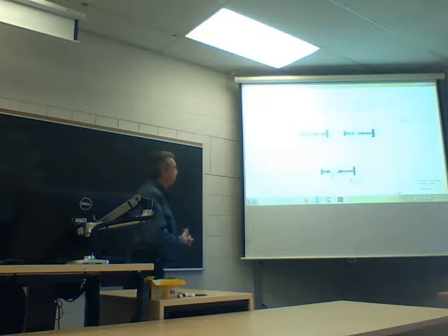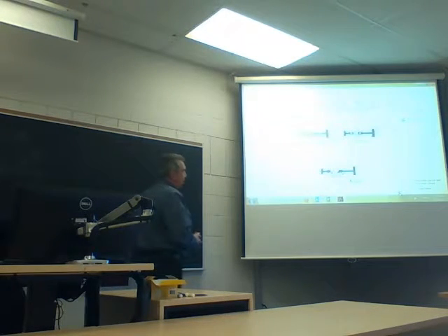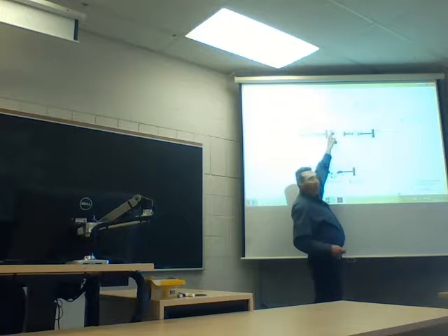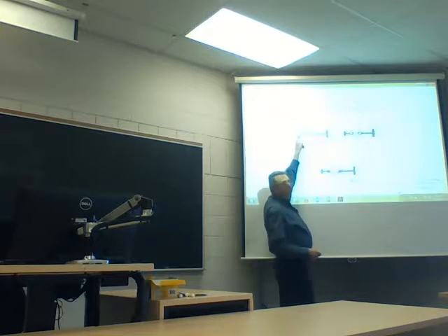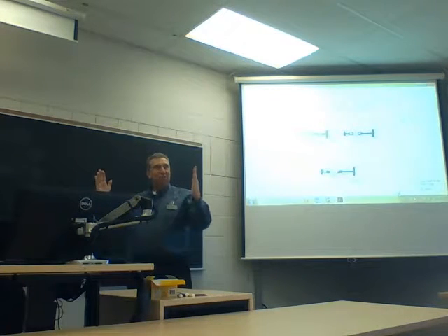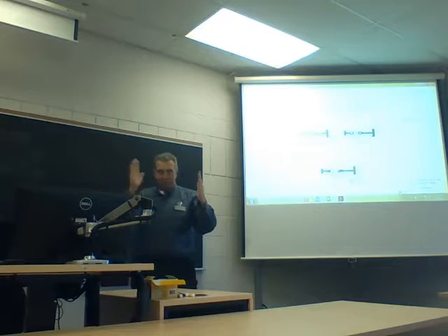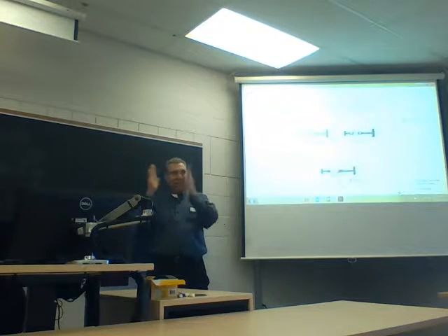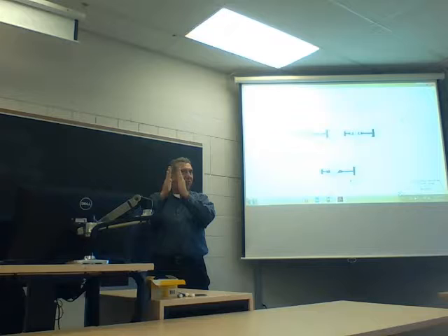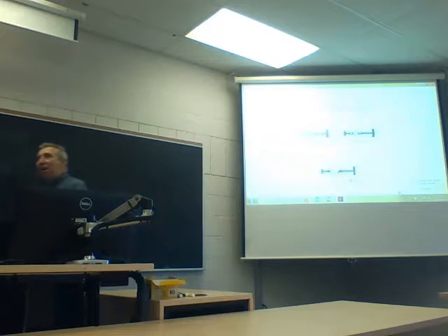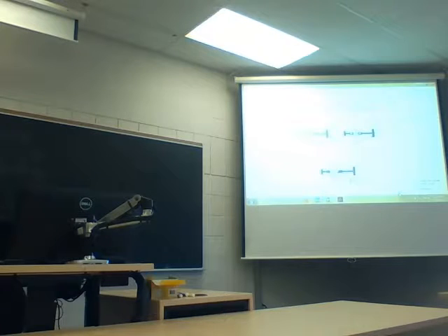What happens is they shoot a little bit of diesel fuel in there, kaboom it goes, drives the compressor cylinder head back, which compresses air, drives this one back into a cushion tank. Gets back to the cushion tank, all of a sudden the pressure from the cushion tank pushes that back down, pressure from the air receiver pushes this one back, it gets back together, we shoot some more diesel in there, there's enough heat, wham, wham, wham, the whole day long. And so it can be run really just off of diesel fuel.